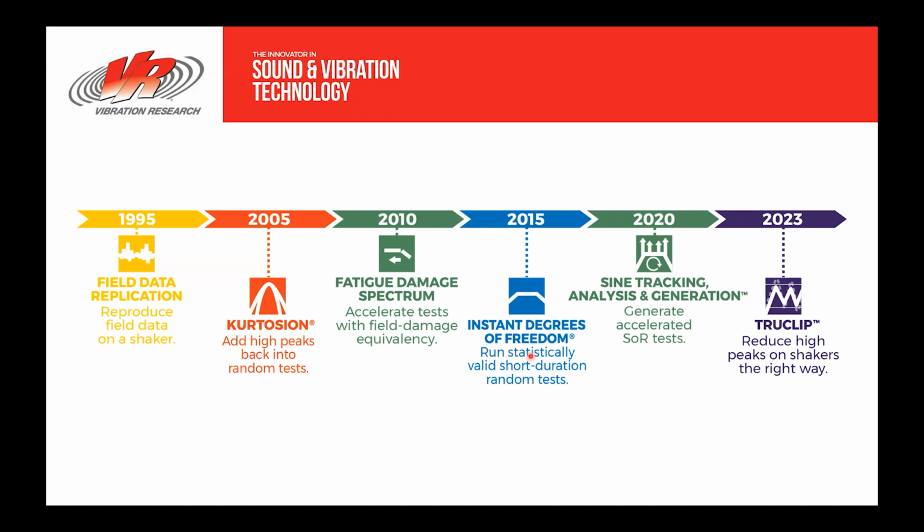IDOF, or instant degrees of freedom, improves the accuracy and reliability of the short-duration random tests commonly used for expensive launch systems and complex payloads. It uses an advanced and patented algorithm to deliver accurate and low-variance PSD estimates, calculated much quicker than traditional averaging. IDOF removes the estimation error while displaying the control error, providing the true difference between the PSD of the signal and the demand.